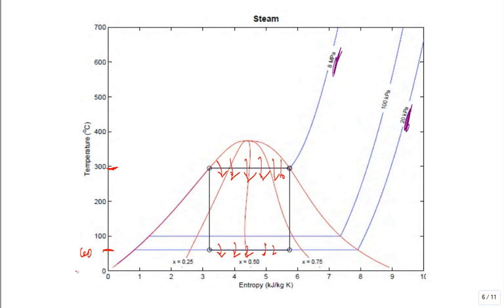Somebody says, why do you peg the corner right here? This was state 1. Couldn't I put state 1 right here, where the quality at state 1 is 90%, not 100%? And could I move state 4 from here to right here, so that the quality of state 4 is 10%? Could I run that problem too? Would I get a little rectangle that looks like this?